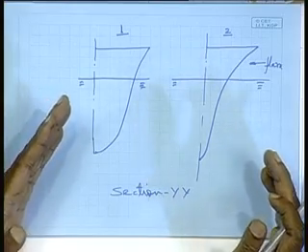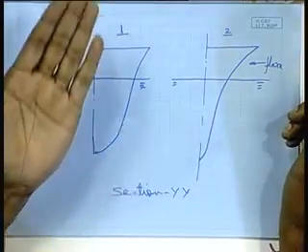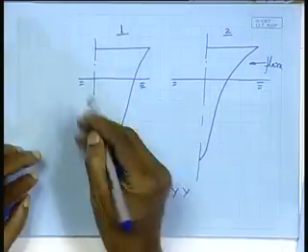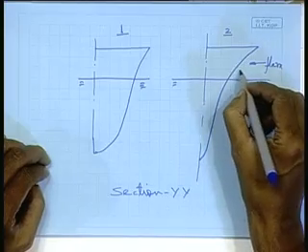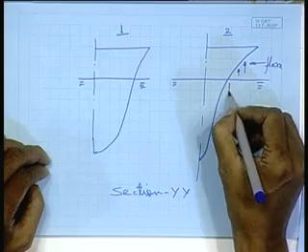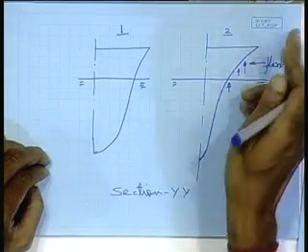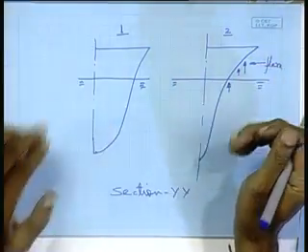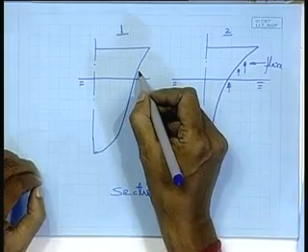In these two forms, as you can see, if both the vessels are plying and imagine it meets somewhat rough weather and the vessel starts heaving. Heaving means it goes vertically up and down. Heaving is this motion, goes vertically up and down, or for some reason if it slams, it is as if about some horizontal axis it is oscillating, that is slamming, right. So, either heaving or slamming, in both the cases this type of form is going to experience much higher loading in this area, because this surface is bigger, it will go on hitting the water surface, whereas in this the load will be somewhat less.